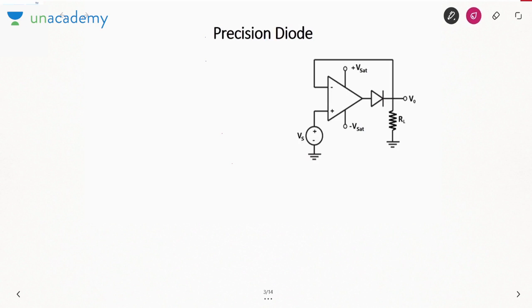How to do that? How did I tell you to simplify any circuit involving a diode? We apply either the open circuit or short circuit test. So I am using the open circuit test. Why so? Because we never know the output current of the op-amp, so it is always better to use the open circuit test when we are talking about op-amp circuits. So this is open circuited.